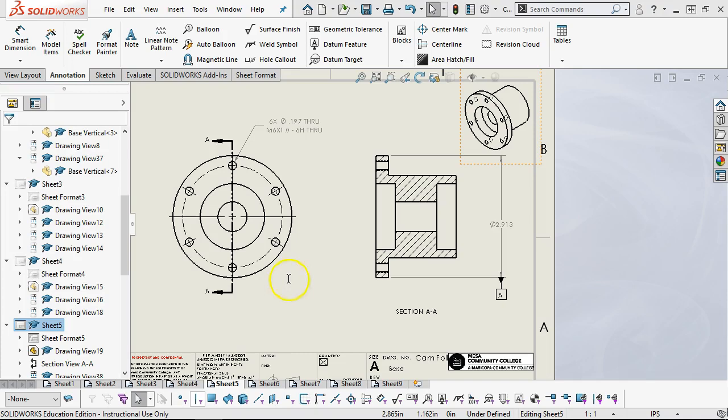So it would have a tolerance in the range of, like I said, 4 thousandths to about 4/10 of a thousandth. All right, so those are going to drive the numbers on picking up that bore. So since we haven't done a limit dimension, then we'll update the precision to a limit and go to 4 decimal places.